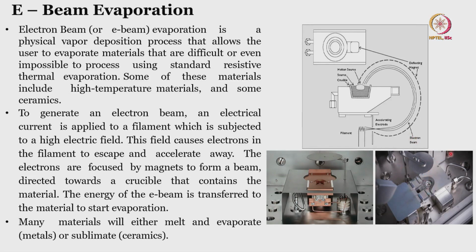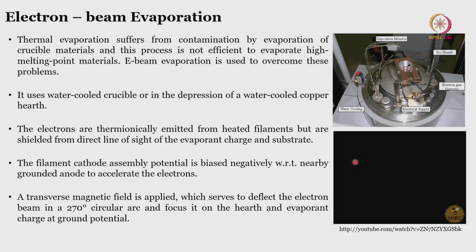So somewhere in this chamber there is a quartz crystal monitor. This quartz crystal monitor, as you know, quartz is a piezoelectric. It is used to measure the thickness of the film. So when we get the right thickness, or rather the right rate of deposition, we can open this shutter and allow the material to get deposited onto the substrate holder. So the role of the shutter is to shut off this particular deposition until we get the rate of deposition that we desire. Now if I go to the next, there are different kinds of source holder. I'll talk about it later.